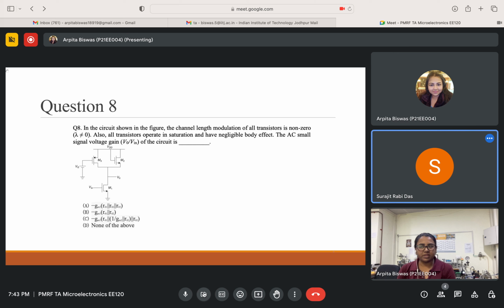In Piranha, chemicals like hydrogen peroxide and H2SO4 are used, with the ratio of H2SO4 to hydrogen peroxide I think 3:1. They mix them and then clean the wafer. So it is a strong cleaning process. It is only to make the wafer good, and that wafer is actually used in ICs and all. When you are working at micron size, a dust particle also has micron size dimensions.